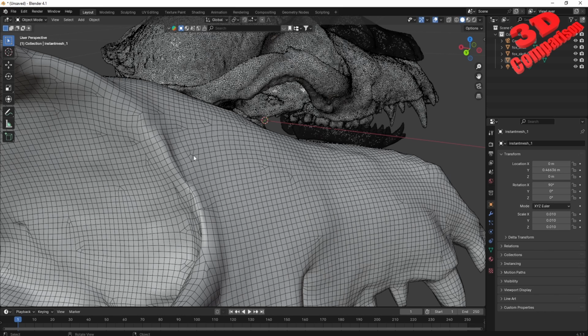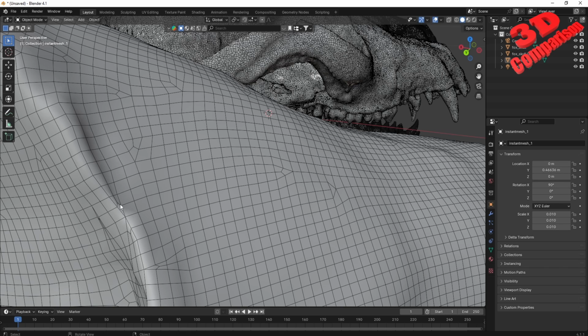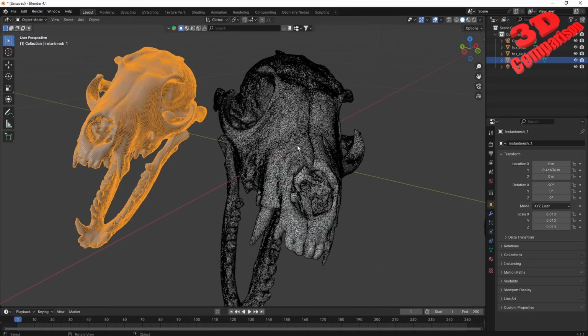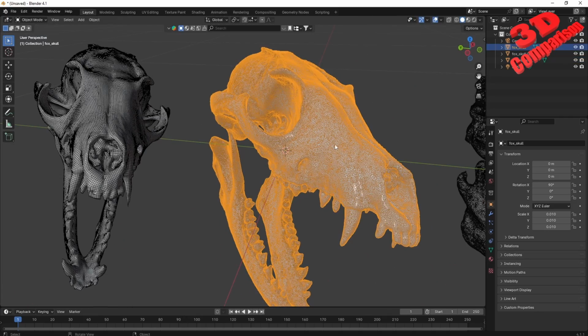Now, there are some instances where we still have some shapes that resemble triangles over here, but actually those, as we can see, will be quads. So for example, over here, if I will select this, I will press tab, go to edge. We have one edge over here, one edge over there. So we still have those 4 edges that define a surface, so they will not be a triangulated mesh. That is the main difference from the previous one.